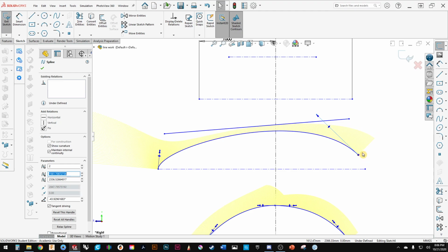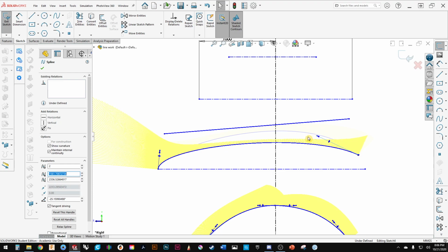And when we talk about acceleration, the acceleration of a curve is equivalent to when a surface starts to contour quicker or faster. And that is where you'll also hear people talk about, as you look at a product, grab something that has a lot of highlights when you get a chance and turn it in the light, but turn it at a constant speed, you will see that the highlights, as they go in certain areas, feel as if they're going faster or slower. That's because that surface is accelerating and curved like this versus just all flat.